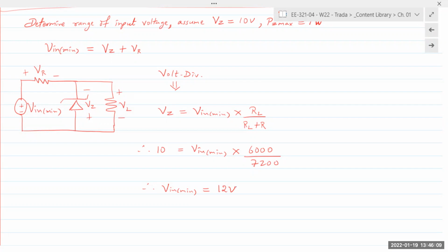So the cheapest rectifier circuits, like an adapter that will plug in the wall, as I've said, I've seen circuits where they didn't even have a PCB. It was just diode components twisted together, and that's it, with tape wound around it. And those cost like $5-6, equivalent in US dollars. So there's no design consideration. They take 4 diodes, twist them together, there's a capacitor and there's another Zener in front of it, and that's it. That's the cheapest. Other than that, that's the lowest end.